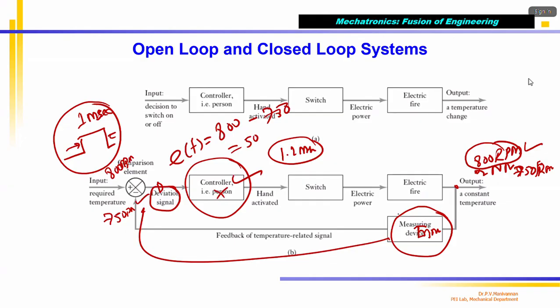It measured using a sensor. This is called a feedback sensor. Now once the fuel is injected, now I'm going to open for 1.2 milliseconds, the torque becomes more, correct? The engine reaches 800 RPM. Why? I injected more fuel, correct? Because the air mass is different.